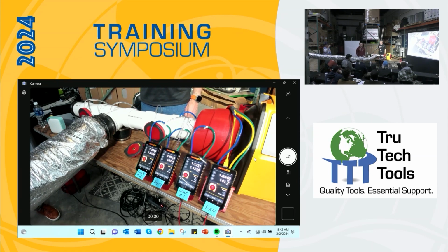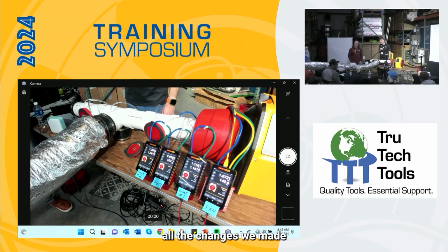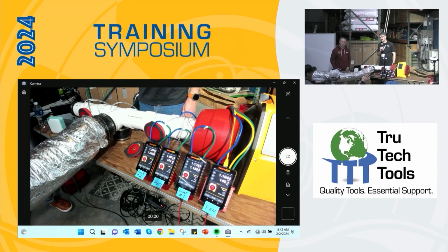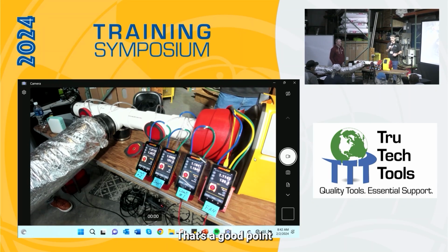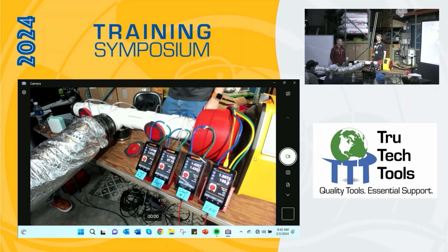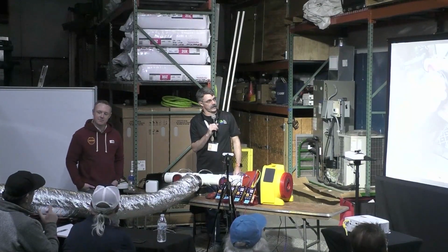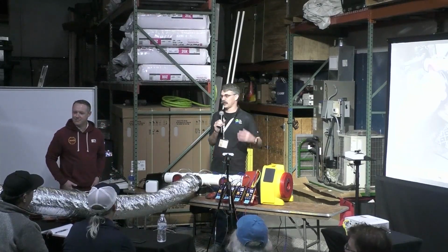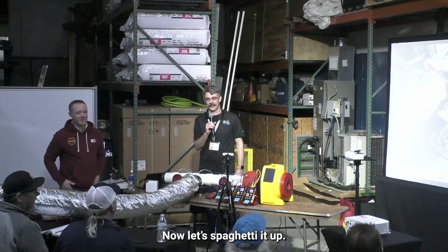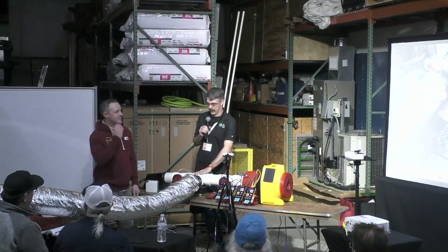50 feet is a lot to ask for 100 CFM. That's a long run for 100 CFM. Yes, the higher the velocity, the more it's going to change, the bigger the changes are going to be. And there was a kink in the duct. That was that scissor truss where it got squeezed in, right? All right, turn it into a big piece of spaghetti.